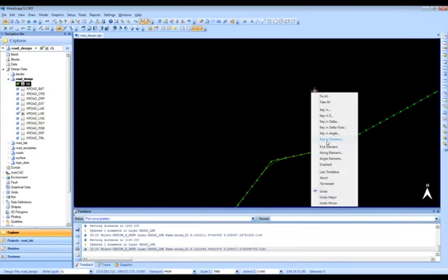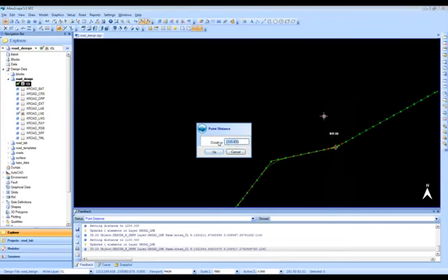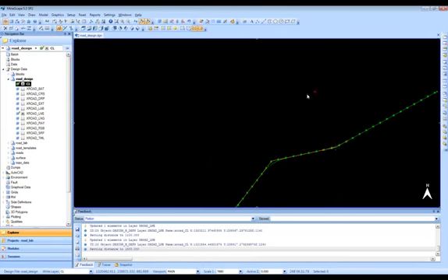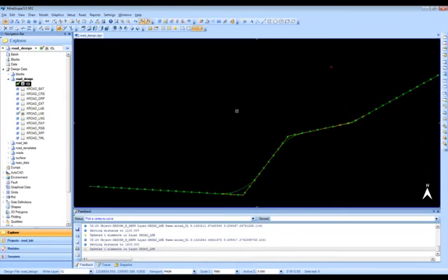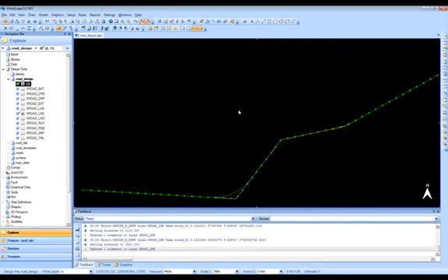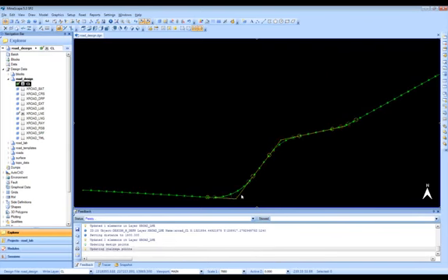And again, I'm just going to key in 1500 as my curve radius. So when I'm completed with this, I can just hit quit, and then my stations get transferred to that new horizontal alignment. So my stations are actually along the new center line, the new alignment of the road.